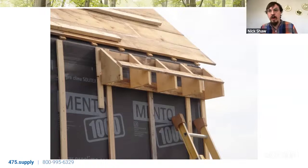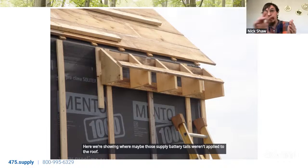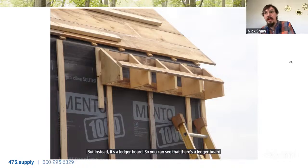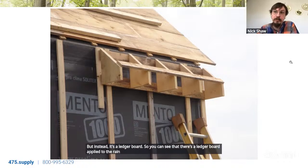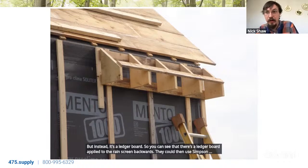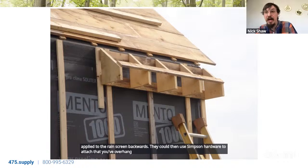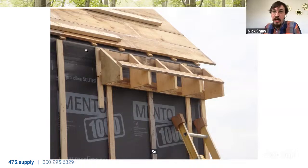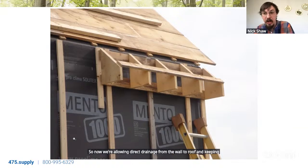Here we're showing where maybe those applied rafter tails weren't applied to the roof, but instead is a ledger board. So you can see that there's a ledger board applied to the rain screen battens. They could then use Simpson hardware to attach that eave overhang. And what I like about this approach is that ledger is attached outboard of that rain screen. So now we're allowing direct drainage from the wall to roof and keeping it within our drainage plane.